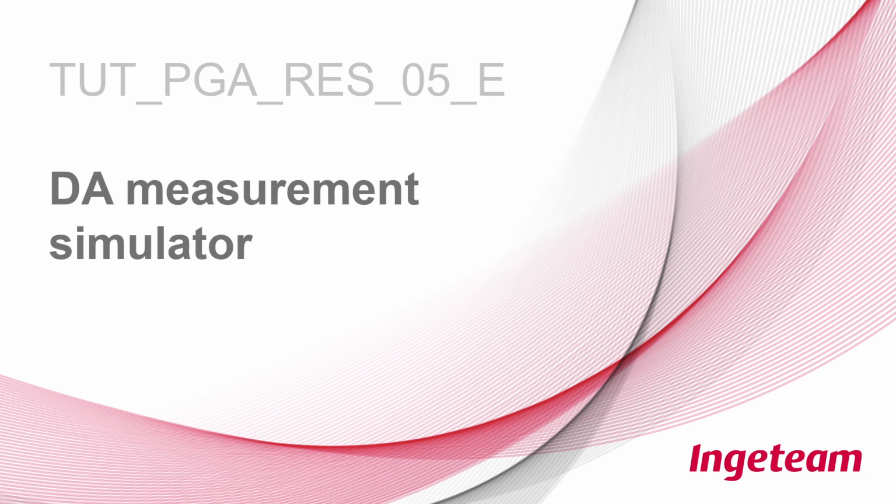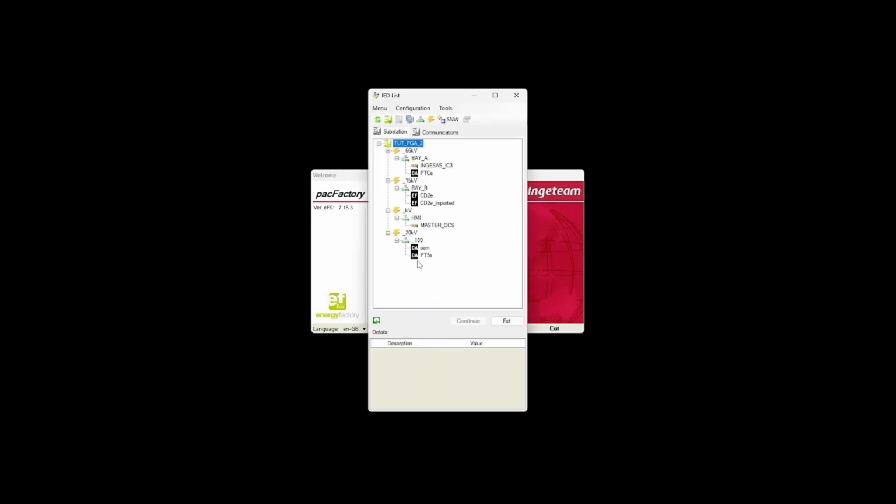Tutorials. Topic: DA Measurement Simulator. In this video we will learn how to use the measurement simulator for the Ingepack DA IEDs, mostly PT1, PT4 and PT5, which is included in the Energy Factory Suite tool. In order to access the simulator, we will first need to open the POC Factory application and select one of the DA IEDs in the installation.